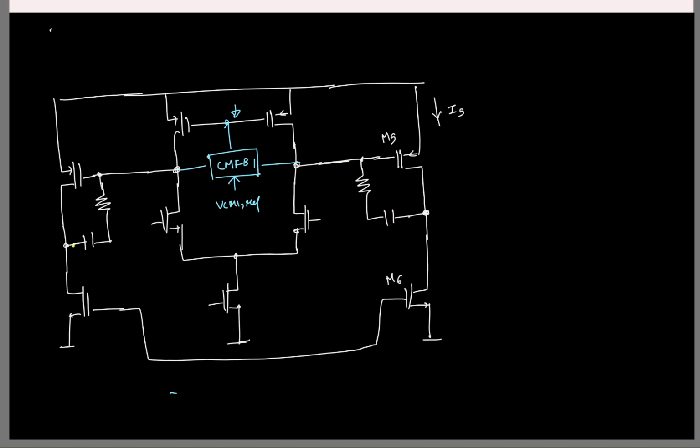Okay, again for the second stage, first let's decide what kind of common mode detector we'll use. So with all these understandings, now tell me, will I use a resistive common mode detector or a MOS-based common mode detector? Outside one, right? Yeah, for the second stage. Resistor. Why? Because after loading one, you can use a resistor. Why? It is driving the load.